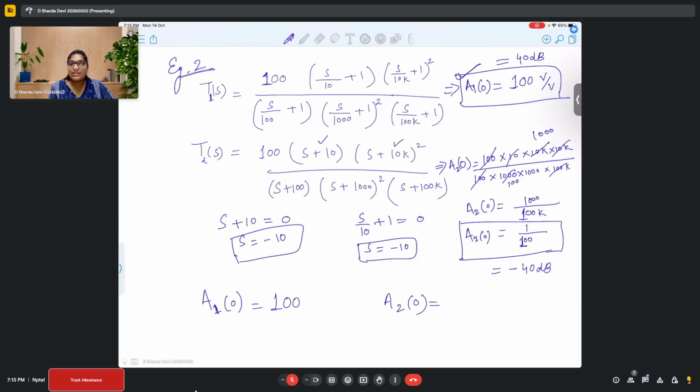In both the cases, your graph is starting from a different point. So when your graph is starting from a different point, according to its poles and zeros, your crossover frequencies will be different, right? Yes. There might be a possibility that the second one, which is starting from minus 40, might not come above 1 dB. That is also true. So the gain might be always negative, right? True.